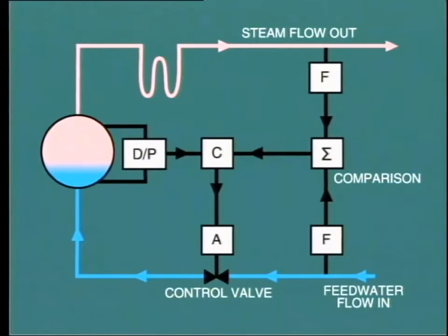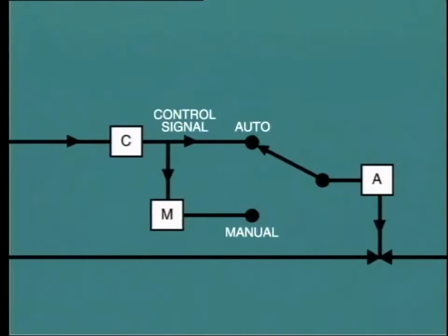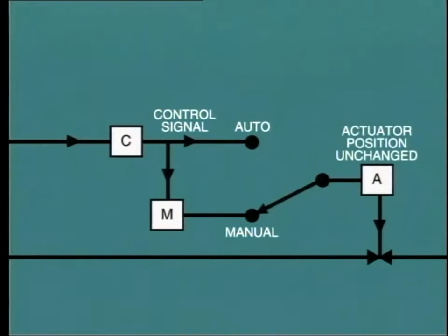One very important feature of any control system is that it must provide smooth transfer from automatic to manual operation and vice versa. In most systems, this is achieved by making the alternative selection continuously follow the actual output signals to the actuators. In this case, any switching from automatic to manual, for example, will keep the actuator in the same position till further change is made.